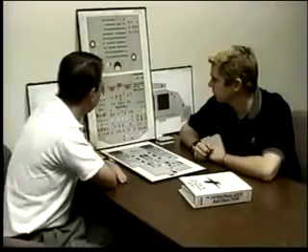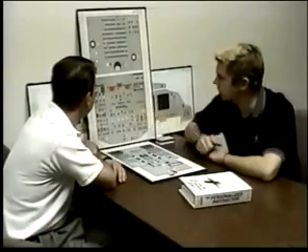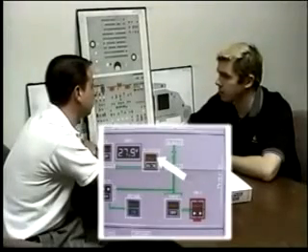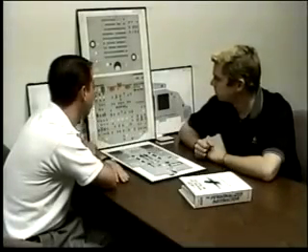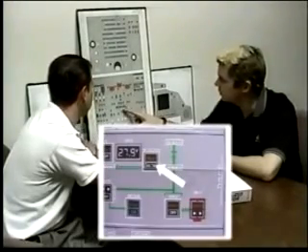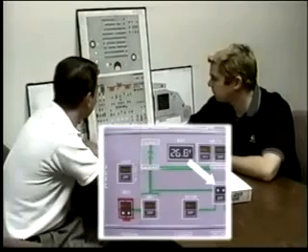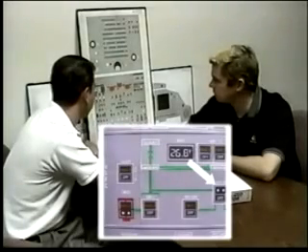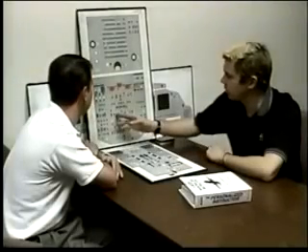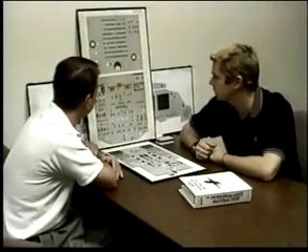Below, I see a title that says AC Essential Bus. What normally powers that? AC bus 1 is indicated by the thick arrow here on the schematic. And what if you got a fault light in AC Essential feed? That means that AC Essential bus is unpowered. Okay, how could you restore power back to the AC Essential Bus? Select alternate on this switch, and that'll allow AC bus 2 to power AC Essential bus. The bus tie switch, when it's in auto, it's giving us our electrical priority, but what about selecting it to off? Selecting it off basically isolates the system and allows generator 1 only to power AC bus 1 and AC bus 2 to be only powered by generator 2.